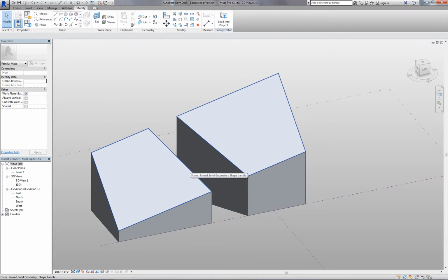The one thing to keep in mind with conceptual mass is that any type of massing we do in this sense is not geometry. I mean, it's geometry, it's a mass, it's a solid. But in building component language, it's nothing. It's just envelope stuff. But we can make real components, architectural components, apply them into conceptual mass, and then load that into the project. We're going to do that eventually. The conceptual mass will go away, but those components will stick around.